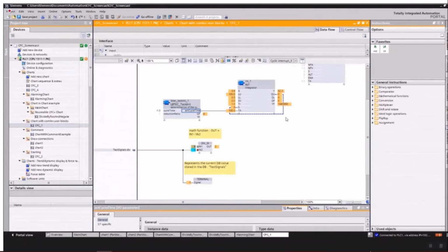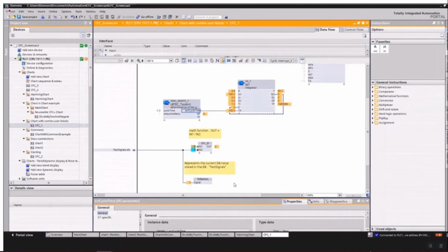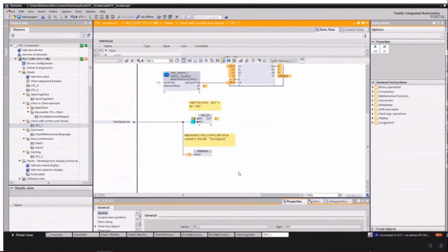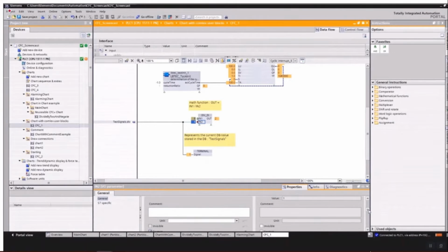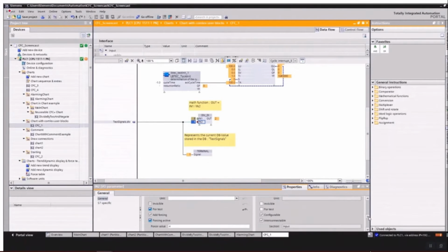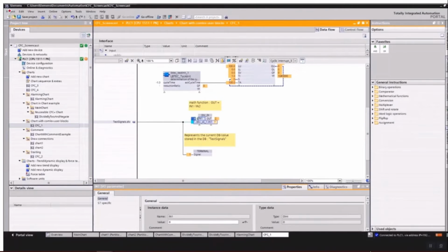The testing phase is not limited to only observing values. By setting the option to force values, the user can even force inputs to blocks that have a connection. But note, the activation of forcing requires a software delta download. I will show you this in the simple example of a block that is used for a double integer division. Just type in a new value and look at the output of the div block.